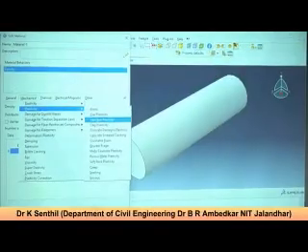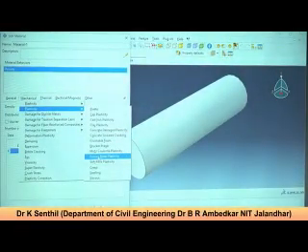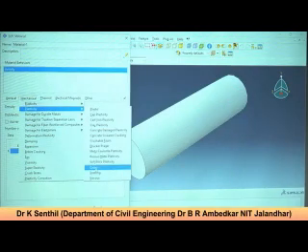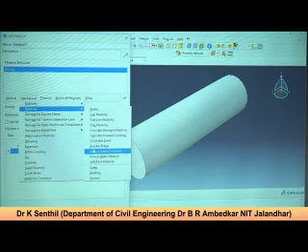Can you see here porous metal plasticity, creep model, swelling, viscous, Mohr-Coulomb plasticity model, Drucker-Prager model, right? So you can select whatever you like. But those material parameters are very important. You have to calibrate, you have to characterize.